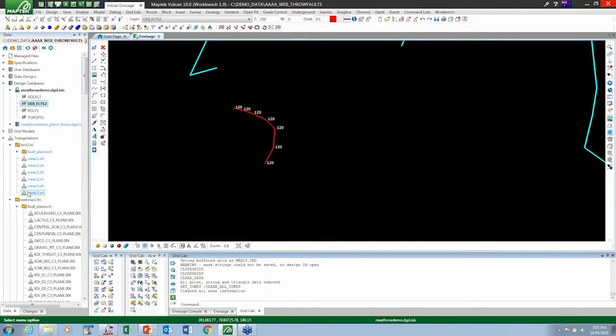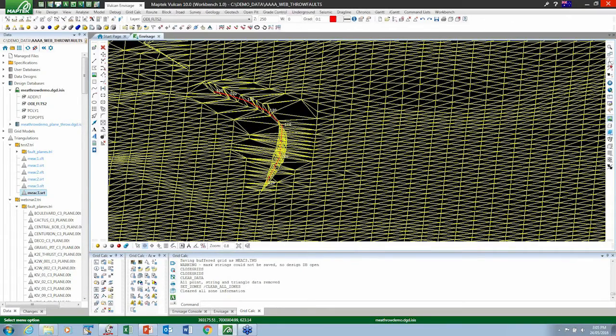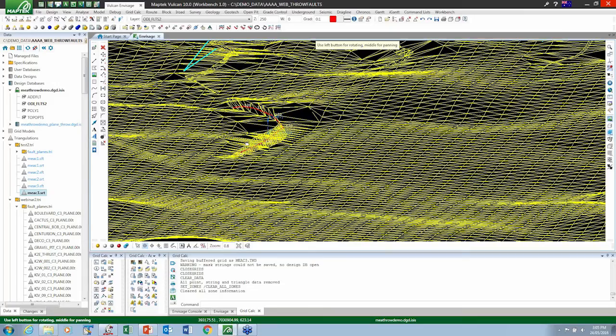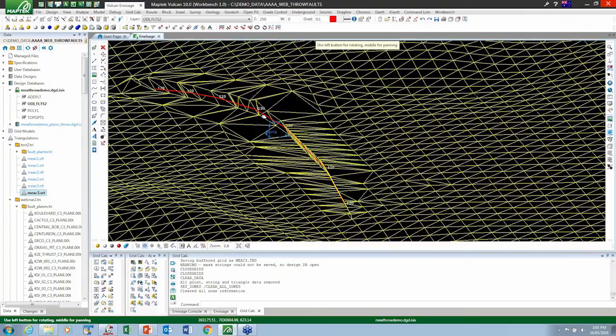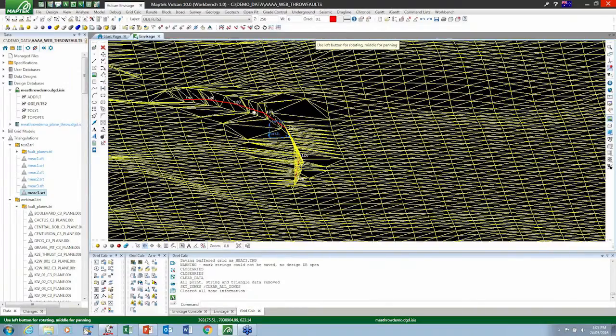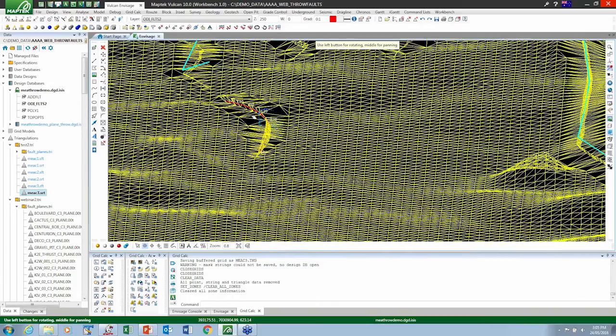You can see in version 10 we get this blue colouring, meaning it's been changed. And if I drag the new surface up, you can see a brand new fault has been imposed into that model, very little effort. And I've guessed the offset reasonably well. Obviously I've made it 40 everywhere, so it looks a bit strange, but I can change the throw. But it's that easy to impose your fault into the surface.